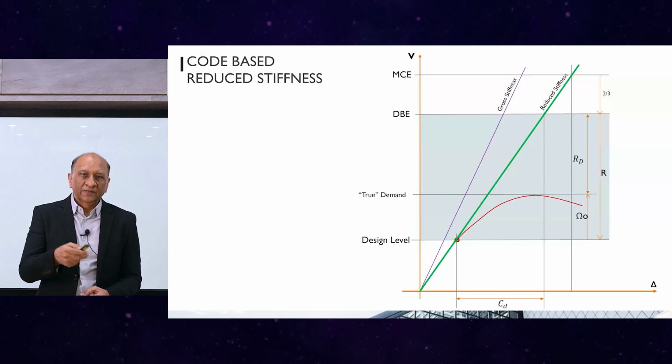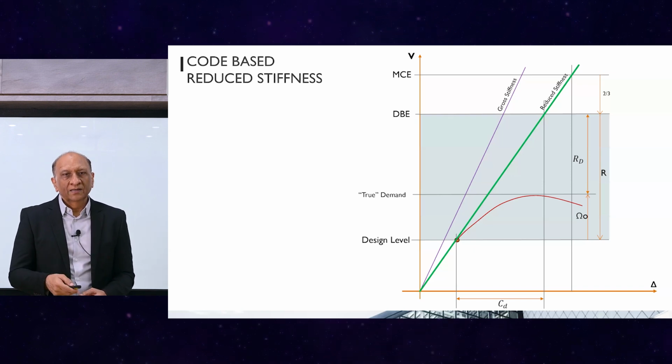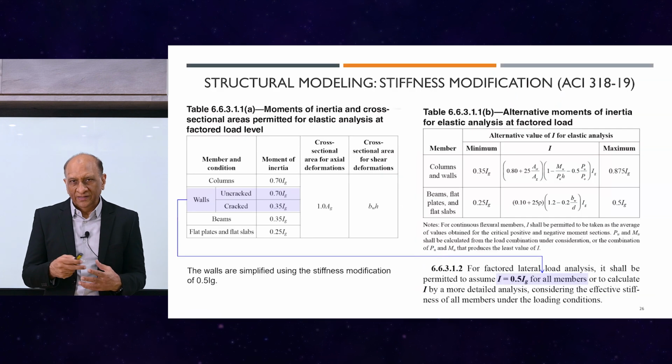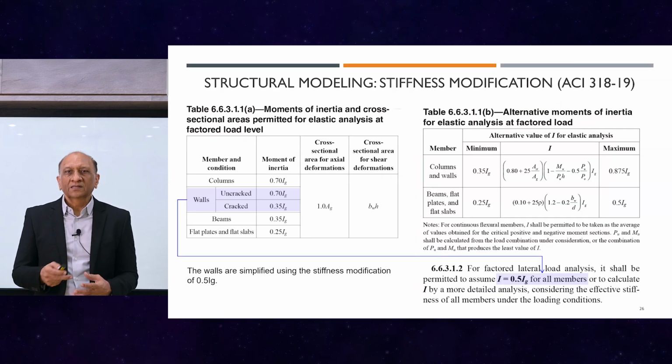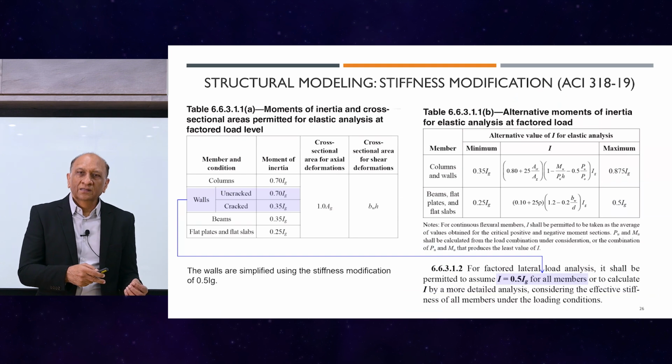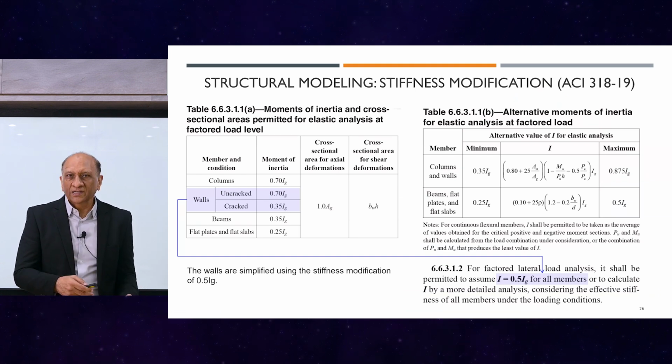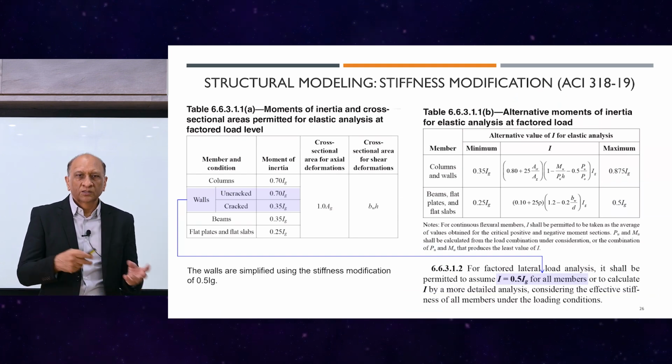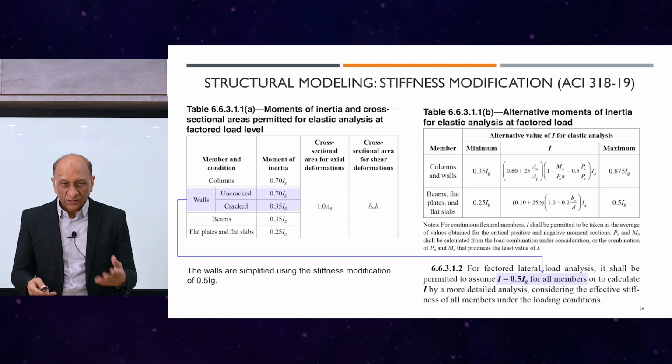And then we have the second mode, also the same thing, reduced from 3 to 4 point something, and then the torsional mode as well. So we can see significant lengthening of the period by reducing the properties of the members from the gross to the cracked based on the codes.